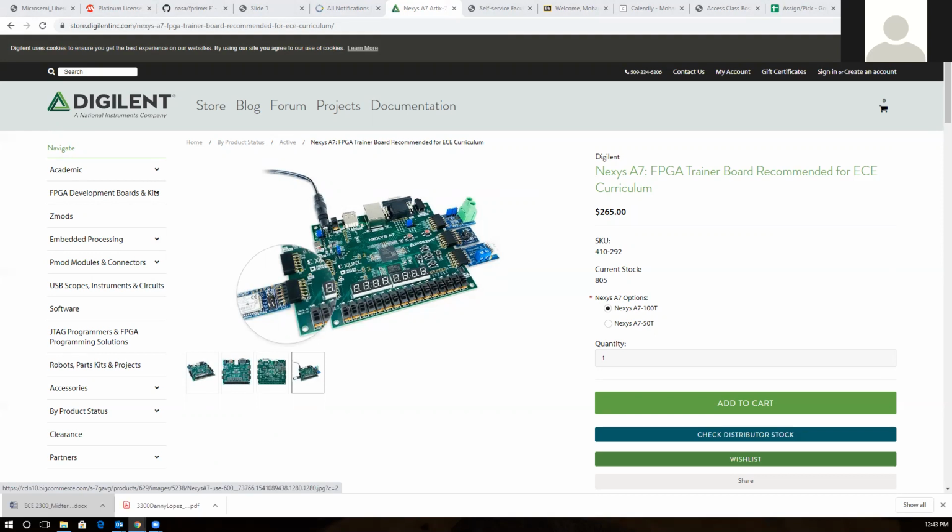It can be like this, a power meter. You connect a power meter and it checks for you how much power you are sucking while the board is doing computation. Then it comes with a charger. You can buy a charger, so it can be a standalone charge, or you can charge it like what I'm doing now. I'm taking the power from the JTAG. So I program it and power it from the JTAG.